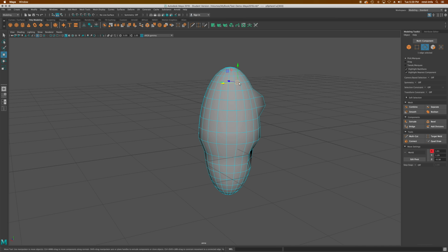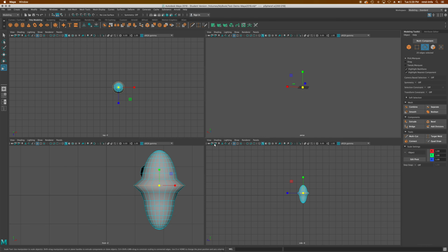We'll talk about this again later, but if you hold down shift and double click an edge right next to an existing edge, it'll select a whole ring of edges. Now I can scale those out and create kind of a ring form. There we go. Sorry, I hit a shortcut key by accident. Now I've got this little ring sticking out around it, right?